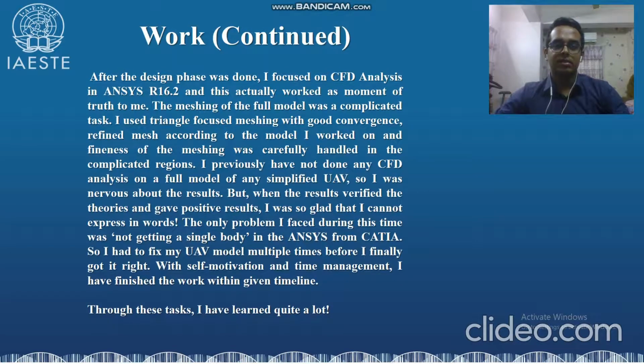After the design phase was done, I focused on CFD analysis in the ANSYS R16.2 version, and this worked as the moment of truth for me, because after the analysis was done, I could really tell myself that yes, this specific design would really work. So the meshing of the full model was a complicated task. I used triangle focused meshing with a good convergence, as I told you before, and a refined mesh according to the model I worked on, and the fineness of the meshing was carefully handled in the complicated regions.